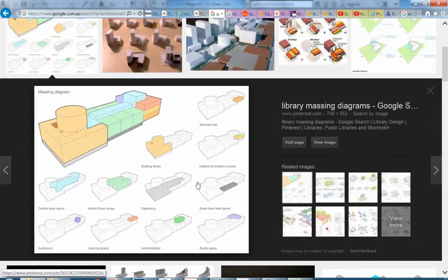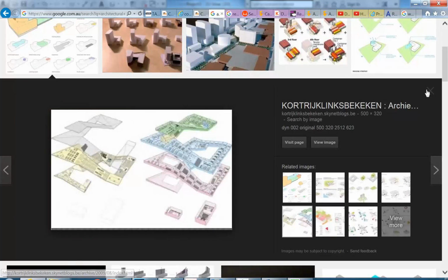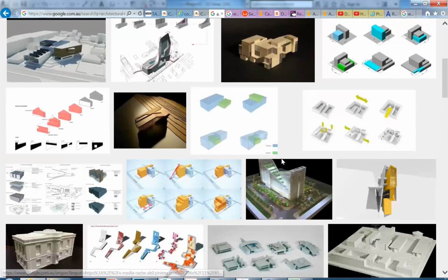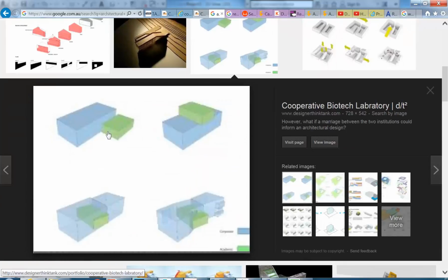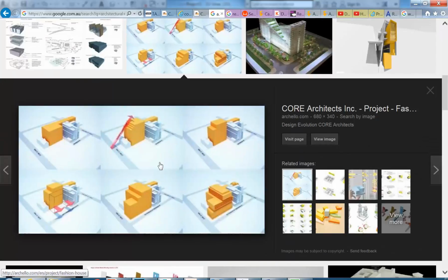For concept level presentations, just to show the block layouts of your design, they're really useful. And so you can see some different examples here. There are plenty of them. So these are all separate mass objects, and you can give them different materials. And this could just come straight out of Revit. And then you can, of course, make them look a little bit nicer in a graphics program, a bit of Photoshop, and then maybe doing some nice layouts in InDesign. Wouldn't hurt, but again, you can do a lot of that work setting it up in Revit with a mass family.